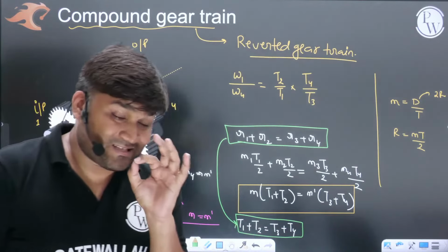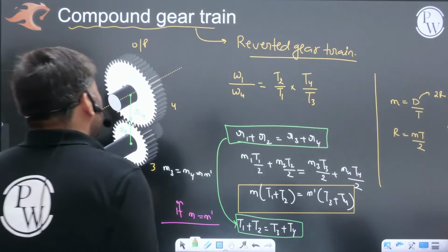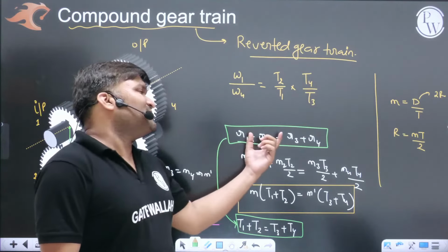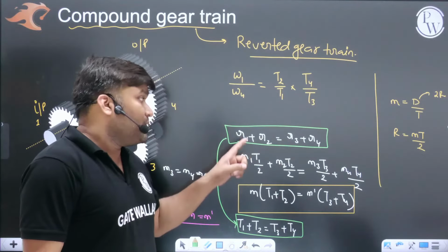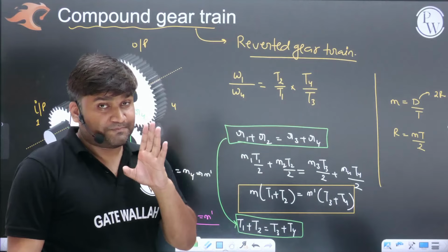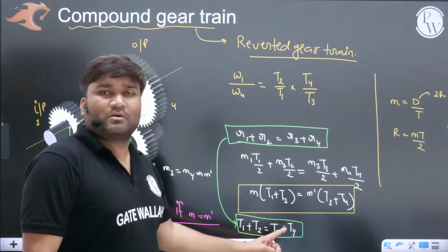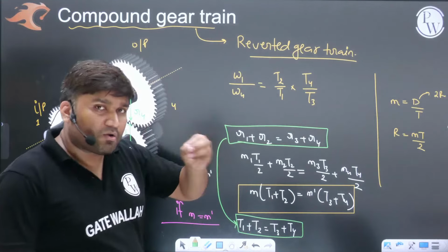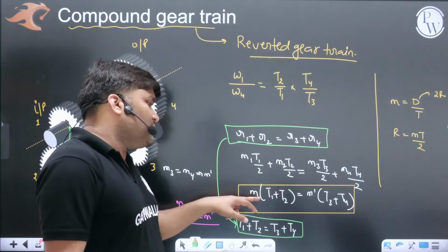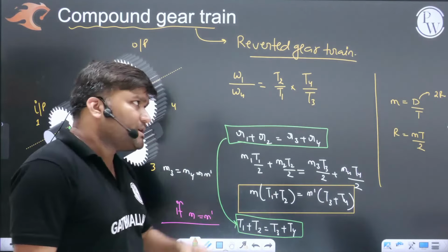But again, listen carefully. In the examination, students are going to commit a mistake here. Why? Students will say, sir, you have told us whatever is the radius relation will be the same as the teeth relation. But hey, I have put a condition also: if all the modules are the same, in that case the radius relation will exactly replicate into teeth. Otherwise, if the modules are not the same, you will have some relation, but module M dash will also be there in the picture, beta. So you have to be extra cautious here. Okay? Achha.